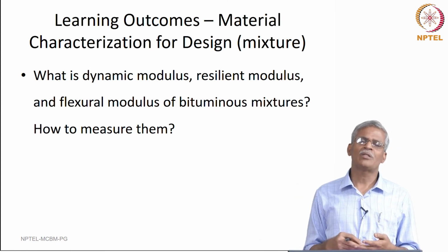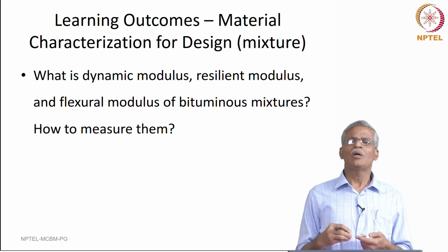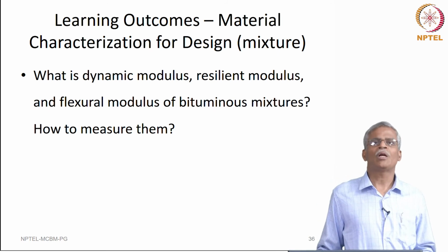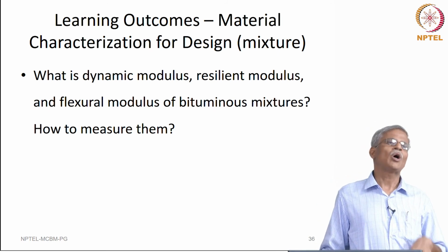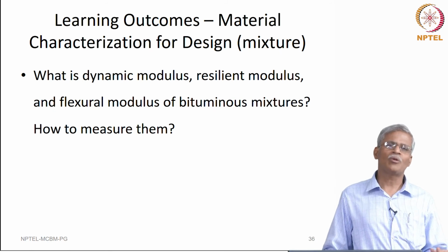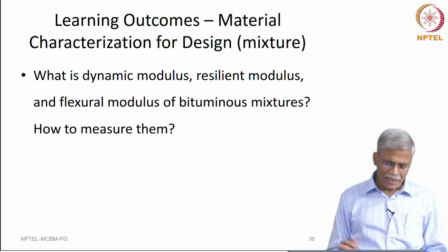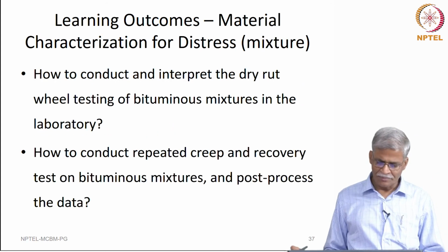In India, for instance, we use resilient modulus, in the United States they use dynamic modulus, and in some portion of Europe they use flexural modulus. So, how do we measure them, how to conduct the test, what is the post processing method to be followed, all this will be discussed in the learning outcome in the material characterization for design.